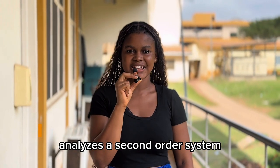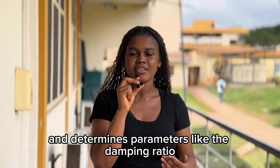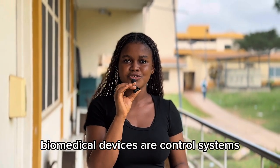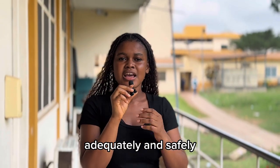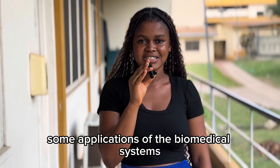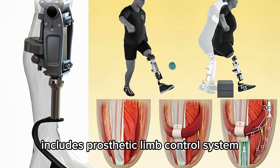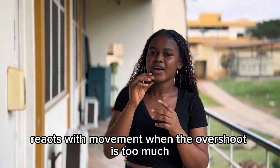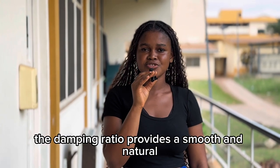The circuit analyzes a second order system and determines parameters like the damping ratio, the rise time, and the maximum overshoot. Biomedical devices are control systems that must respond quickly, adequately, and safely. Some applications in biomedical control systems include the prosthetic limb control system. The rise time determines how the joint reacts with movement. When the overshoot is too much, it causes jerky movement. The damping ratio provides a smooth and natural response.